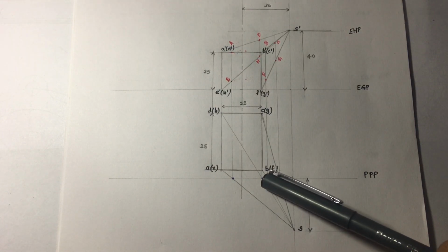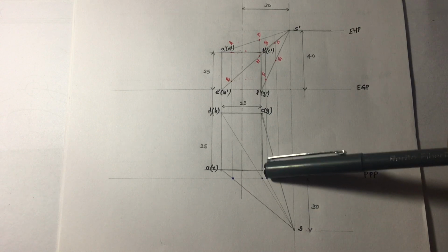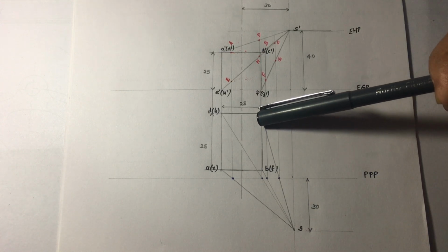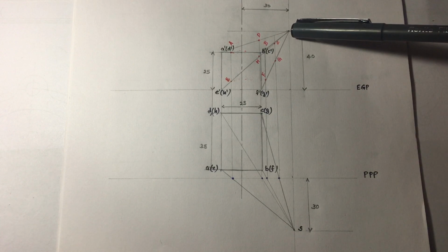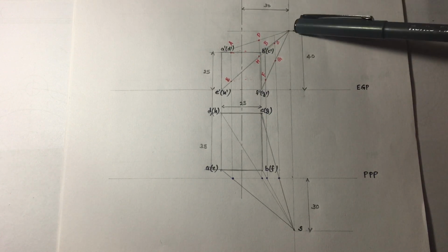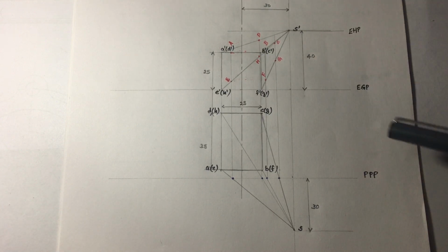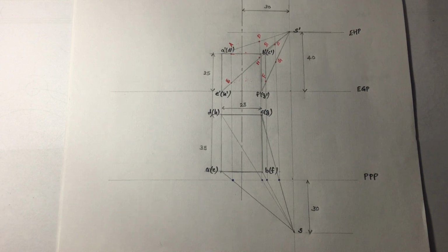This is the intersecting point of SD or SH. So from the intersecting point you are drawing a vertical line, so that will meet on S dash D dash line, and that will be capital D. That will be meeting on S dash H dash line, that will be capital H. Similarly, you have to mark all the 8 points. You will be getting 8 points: A, B, C, D followed by E, F, G, H.